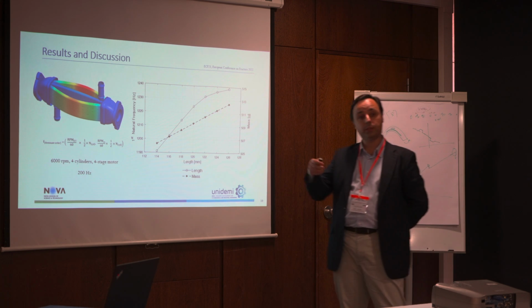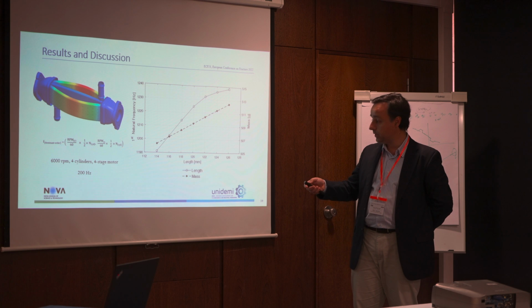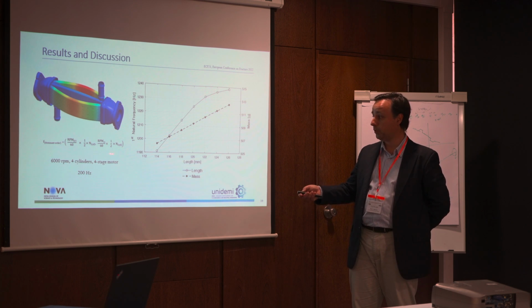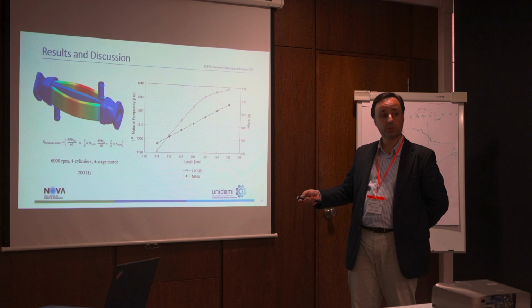So the motor, when it's functioning, for instance, this is a 4-cylinder motor with 4-stage motor, and considering 6,000 rotations per minute, this motor will induce a frequency of 200 Hertz, more or less.